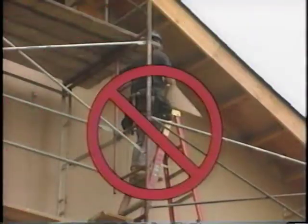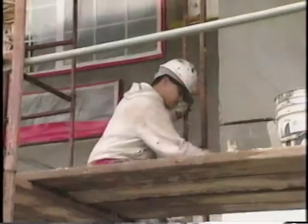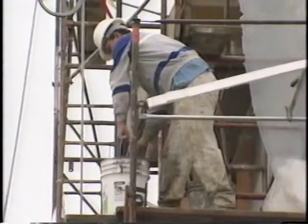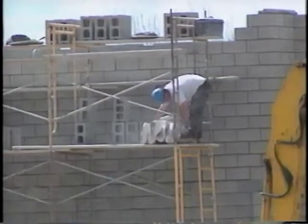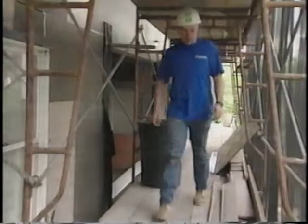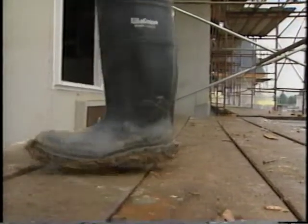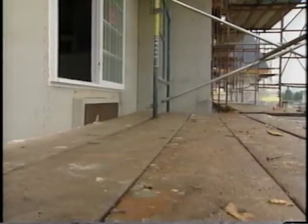Never use a ladder, boxes, or any other means of elevating your height on a scaffold. Maintain complete concentration at all times. Maintain both feet on the platform surface and never extend your body over the edge of the platform or guardrail. Good housekeeping practices can also prevent slips and falls from scaffolds. Keep all walkways and working surfaces clear of tools and debris. Do not perform any work on scaffolds covered with snow, ice, or other slippery material until it has been removed.